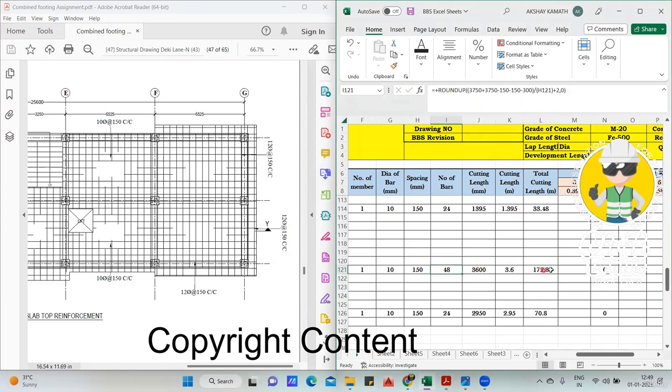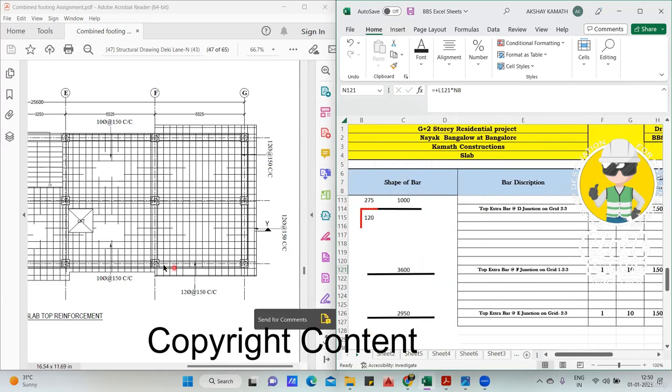This you divide by 1000. Total cutting length. And this will be how much? This answer multiply by 0.617. Finish. Correct, no? Good. Correct. Finish. Last one thing, that quickly we'll finish it off, which is this portion here.